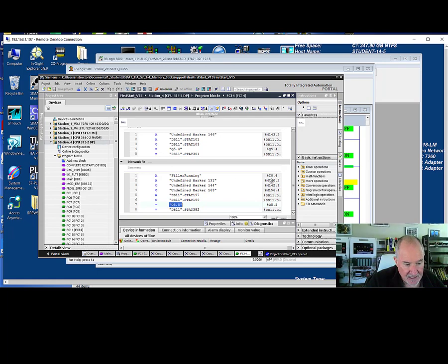If I looked at this and I said, well, I'm expecting for the filler to be running and I0.4 should have been on, but it's not, then I'm done with my search, right? But we're going to go a little bit farther here and pick something else, just so we get a little practice tracing. The way to read this, once again, statement list is a little tricky, but this is saying